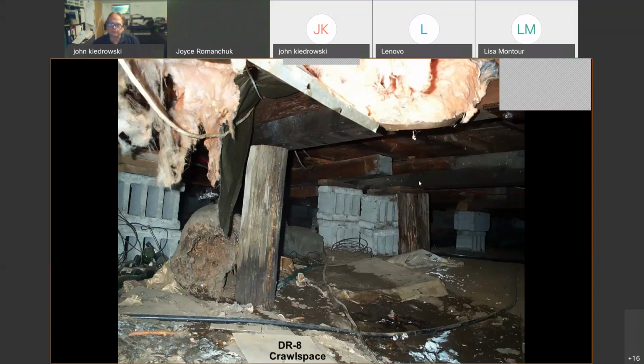into the wood structure. If you look at the wood, particularly on these piers, you'll see where there's water damage or moisture damage. And also probably the darkening of the wood is moisture that's actually penetrated up into the wood. Mind you, it might take a long time for some of these to rot totally out, but certainly with some members that are smaller in size, it would deteriorate much quicker. So again, moisture and water in a house. And if it's going here, it can also migrate up into the floor system, which causes other problems to the floor sheathing in a house.